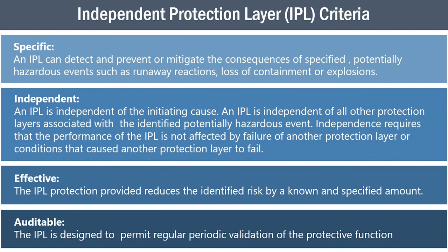Now there's a high-level alarm in there. That high-level alarm automatically will trigger the operator's attention should a high level be reached. Now the question becomes, are those two independent protection layers? The answer may be no, because quite honestly, the operator is the same operator in both. So they're really not independent.